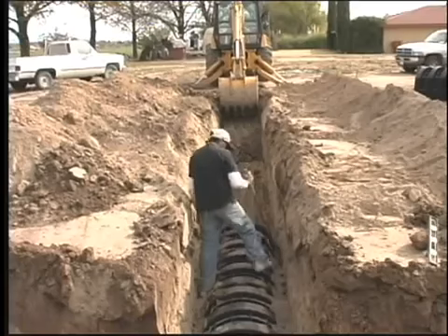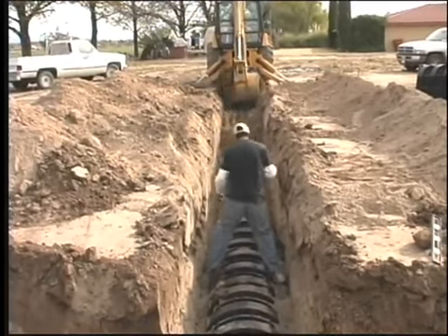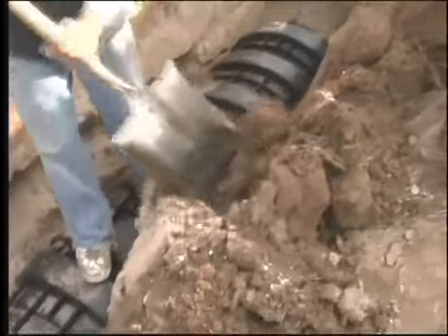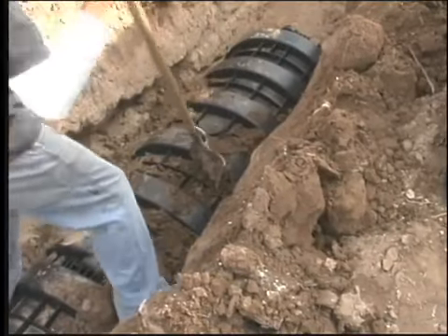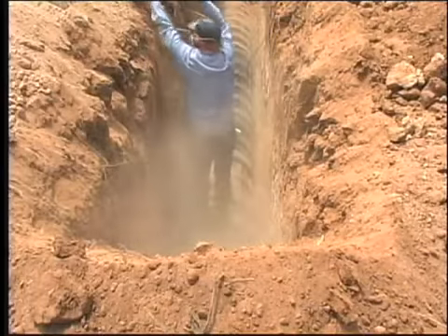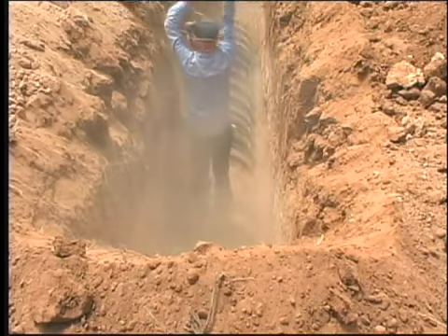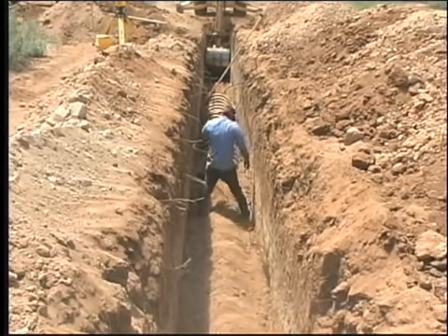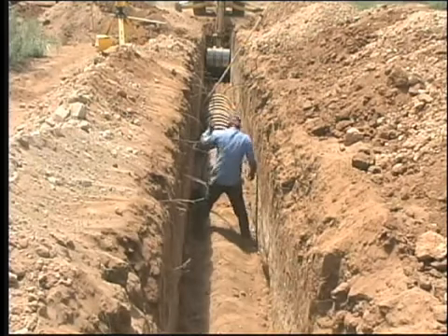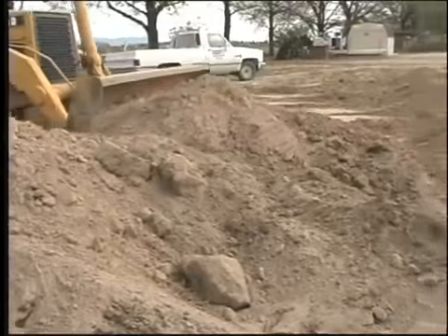It is critical with these chamber systems that the sides of the systems be filled prior to backfilling. This provides support for the arch so that the chamber does not collapse or cut into the underlying soil during backfilling. Fill the sidewall area to the top of the slots with native soil and walk the soil into place. Now the chamber system is ready for the trench to be backfilled.